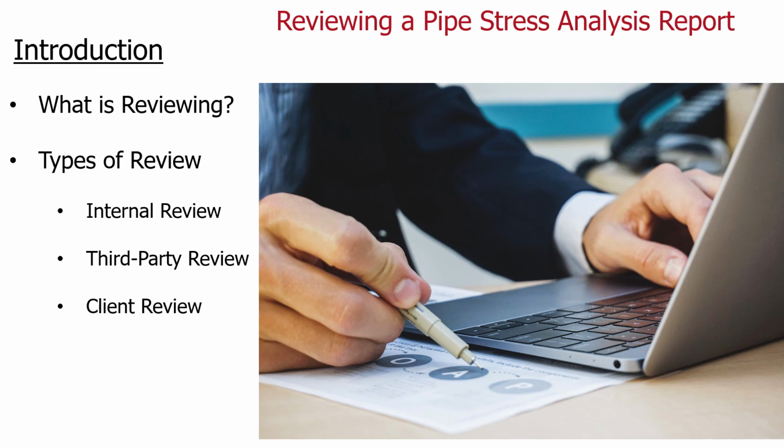And at any stage, if there are any comments, a comment resolution sheet is prepared, along with the proper comments highlighting the sections or clauses from which the comments are coming, so that the engineer who performed the stress analysis can take care during the next revision of the report. So this is mainly the introduction part of the reviewing a pipe stress analysis report process.